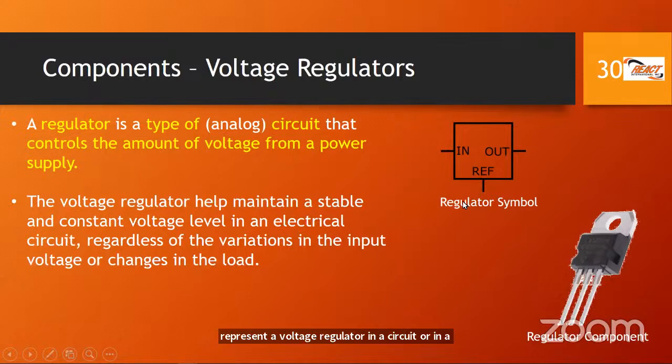And remember, we had said that when we are in a power supply, we might want to convert from the AC voltage that comes out through our plugs or our receptacle outlets in our wall, and we want to convert it to a DC supply for our amateur radio transceiver, 13.8 volts DC. We said that we have to rectify that circuit.